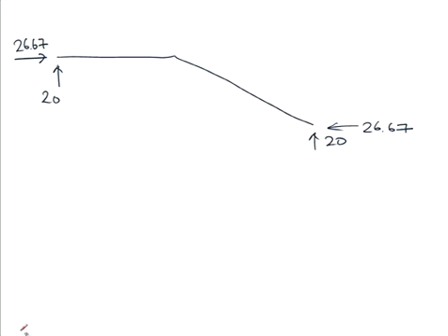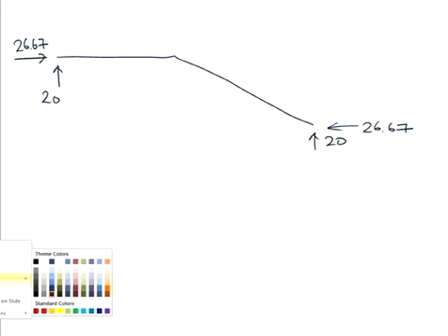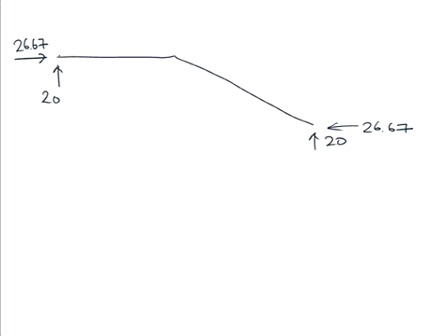So when it comes to drawing my shear force diagram, I stepped up a value of 20. My load reduced linearly, a total of 40. And when I did split it here, you saw we had a reaction of 20, so it steps up. Because what is shear force? We say it's a plot of the vertical force on a horizontal beam. It's actually a plot of the force perpendicular to the axis of the beam. And we have agreed, well, I have told you, and hopefully you can see, that our member BC only carries axial load, so there's no shear in that member.